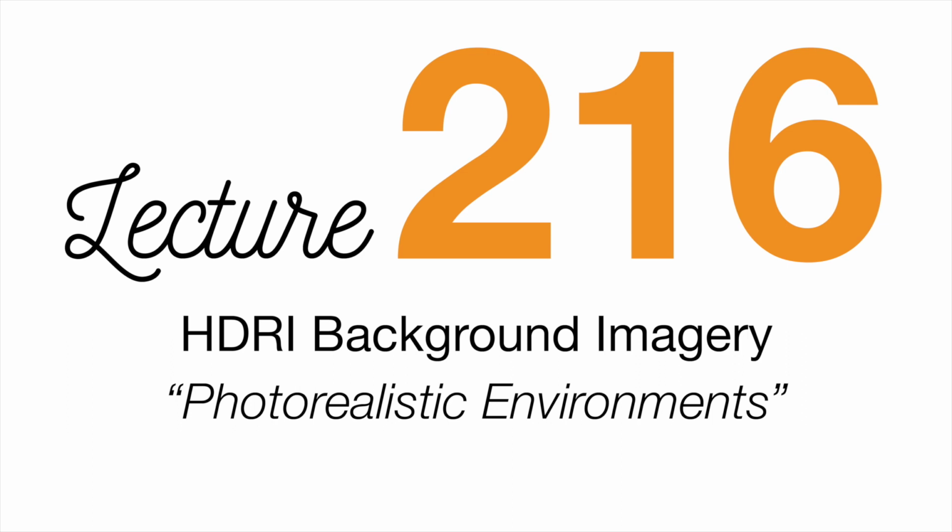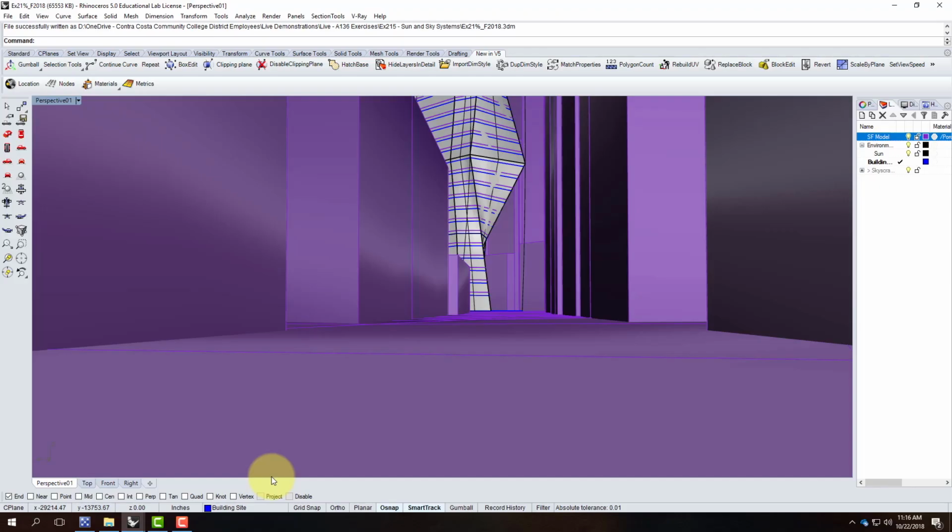Okay, so we're going to get started with exercise 216, and really what we're doing today is we're extending the concepts that we talked about last class a bit further. And the ultimate desire here is that the sky is now going to be not computer generated. It's not going to be based on what Rhino comes up with or V-Ray comes up with as a sky. Instead, we're going to base it on an actual location with actual background imagery. And that can really help with the realism of any rendering.